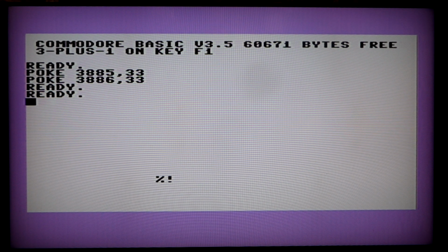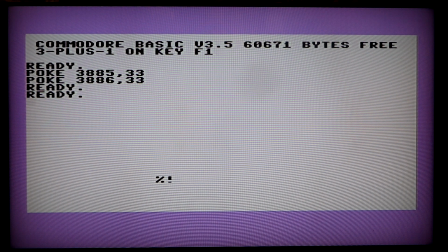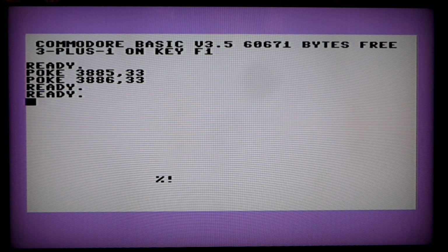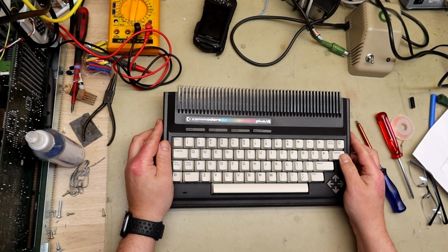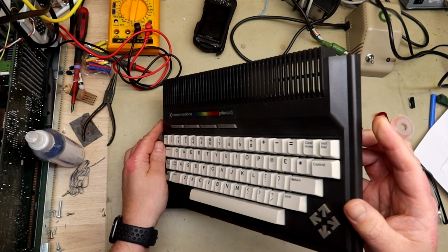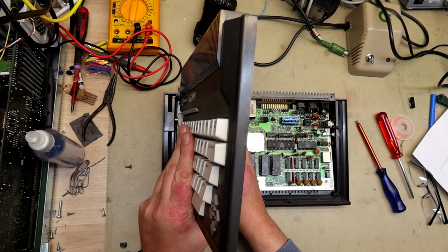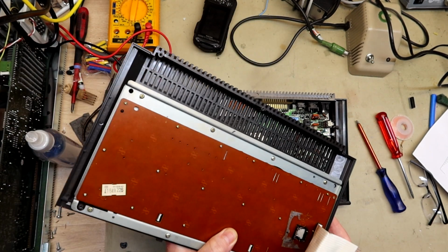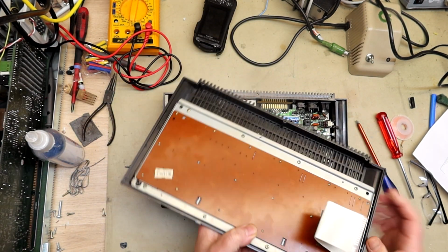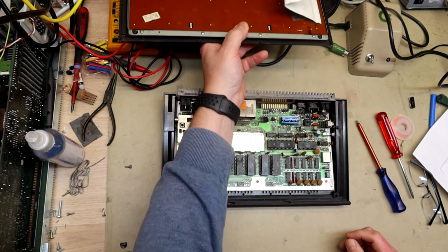And I'm going to desolder that chip, and I'm going to replace it with a socket so that we can put in this memory chip or another to just test it. I'm going to desolder the memory chip, but before I do that I need to take out the main board. You can see this connector for this keyboard is getting tired of being pulled out all the time.